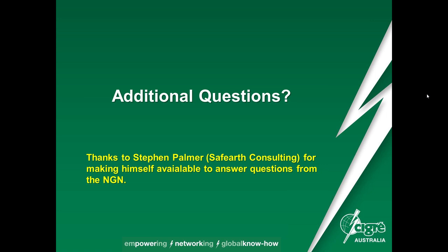So when we say, oh, my understanding has changed about how I should measure whether they're safe enough or whether the risk is low enough, we should be ready to say, now how am I going to roll that understanding out across all of my assets? Now, the way we've done it for utilities that we work with is we've got a fairly high level desktop assessment of all of their assets, and you're almost putting a risk score on them. You can say, look, all of these ones, they don't worry me for these reasons. These ones here, I think we should get to those, but they're not the highest priority. These ones here, we need to assess these for these reasons.